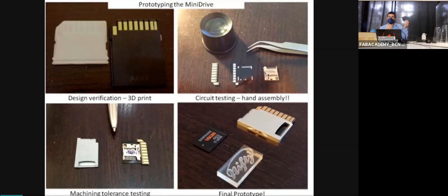So it's the first time you want to produce your model of your SD card holder. You know the final product will be in aluminum. Would you want to cut aluminum the first shot? Never. Why? You need at least 2 hours to set up the files. It's a complex cut, and you're using expensive material. Do you want to first test the geometries, like a basic geometry test? Okay, use your 3D printer. It will be easy, fast, and good to make the setup on modeling, on tolerances.